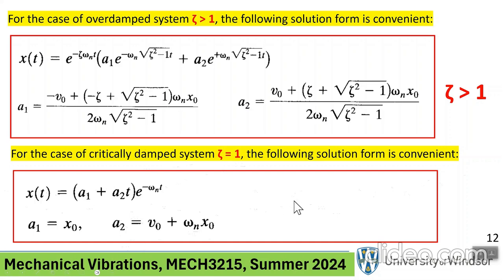There. So we got everything. We got the solution when it's underdamped, overdamped, critically damped, in terms of the two response parameters, that's a fancy way of referring to zeta and omega n, by the way, and the initial conditions affecting the coefficients that make that solution, both in these two cases, and of course in the case of underdamped also. All right, let's do a problem.